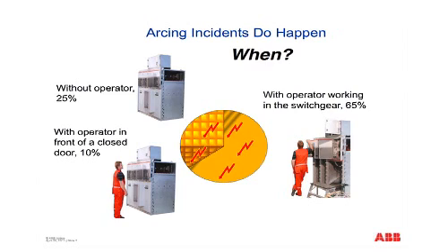Because that's when the person is involved in the gear. And what is he doing? They're messing around with the relays, maintaining the electronic low voltage control, maintaining the breaker, or racking out PT compartments. This is very typical of what happens when you're maintaining metal-clad switchgear.